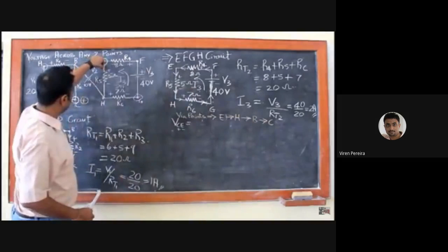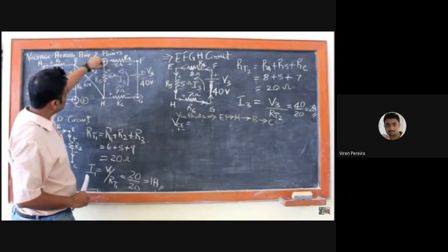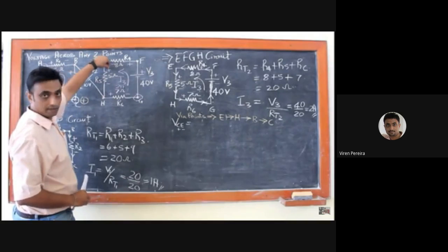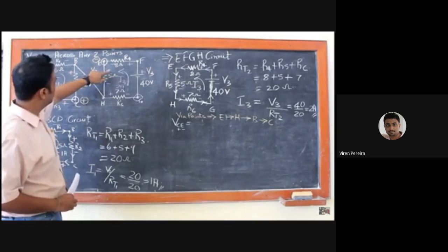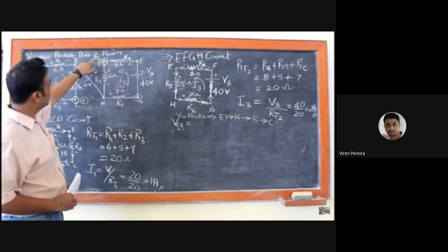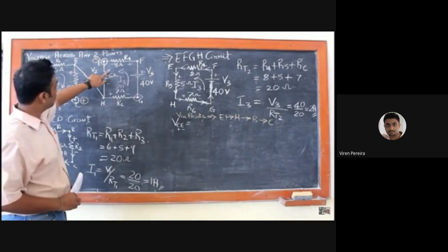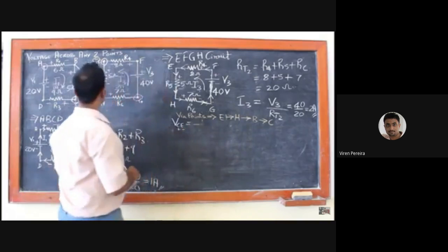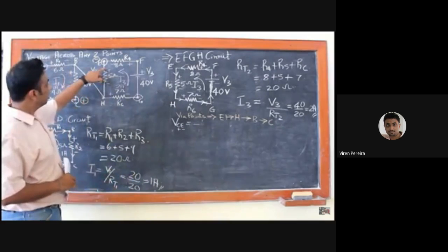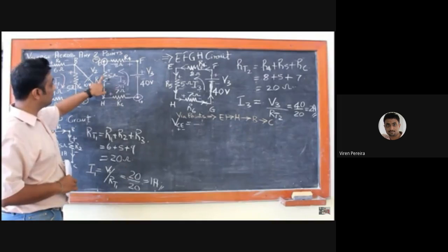So if it is going here, it will first meet the resistor of 5 ohms. The first terminal of the resistor is positively charged. So whatever operator you have here, you have to multiply it with the negative terminal of the multimeter. So positive into negative will give us negative. So I got my sign. Then how many ohms is it? 5 ohms. What's the current flowing in it?